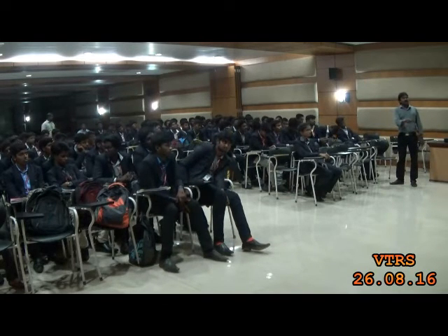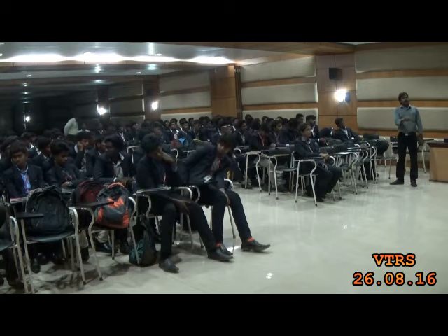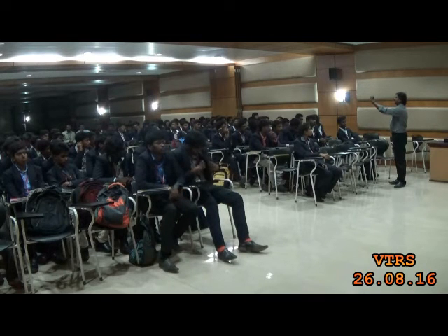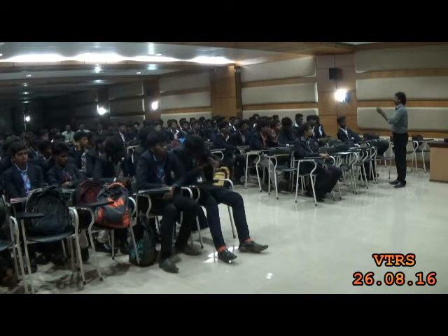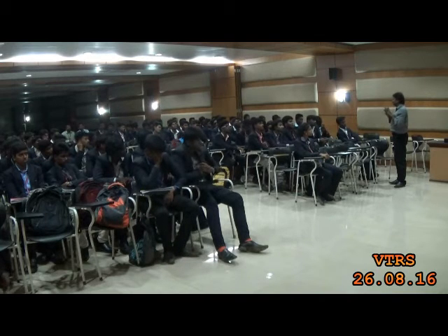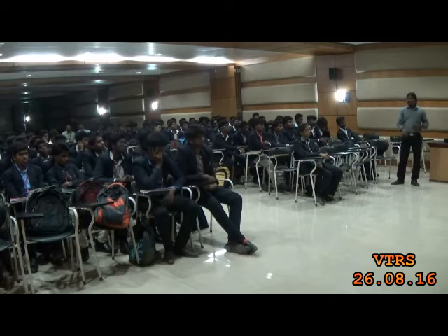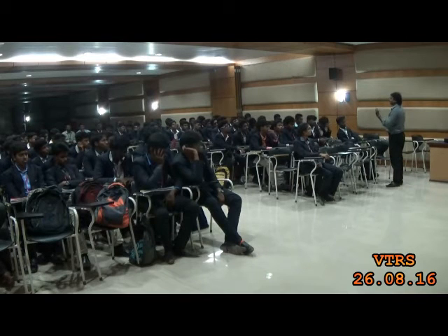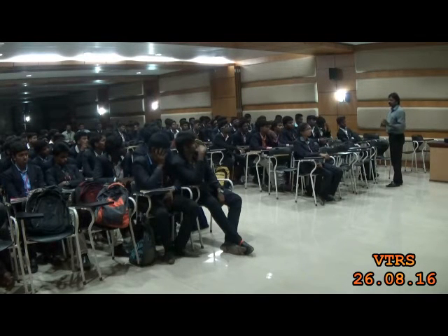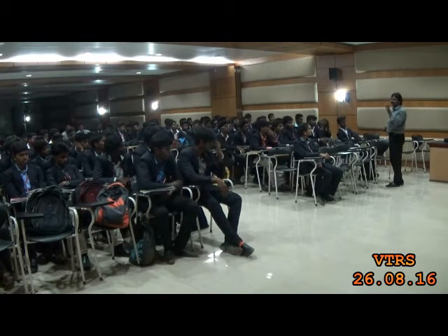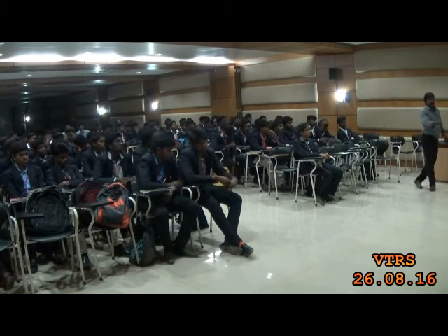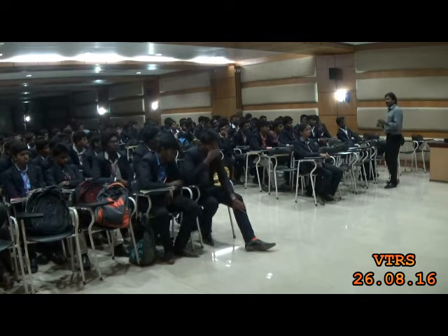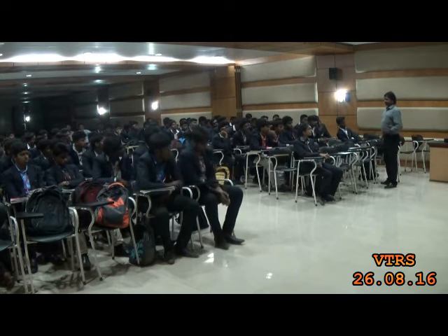So what they do is, this is something called the macro view. After getting something failed, you look at the failure and you need to understand what has happened. The second one is, if you could not observe with your eyes, you put a small piece of the failure area under a microscope, magnify it and look at whether you can see something else. If you still can't find it, you put it under energy dispersive spectroscopy. What you do is find what elements are available in the failed region.